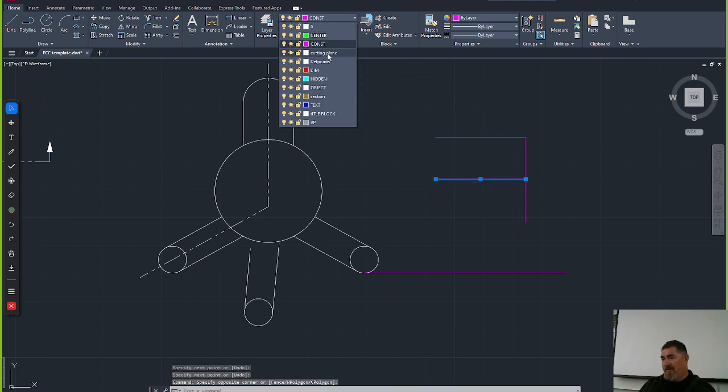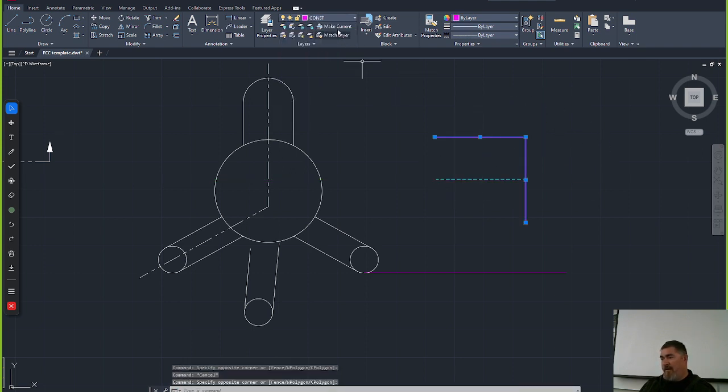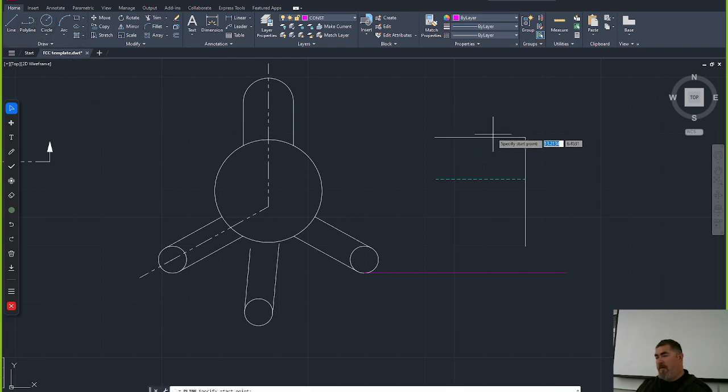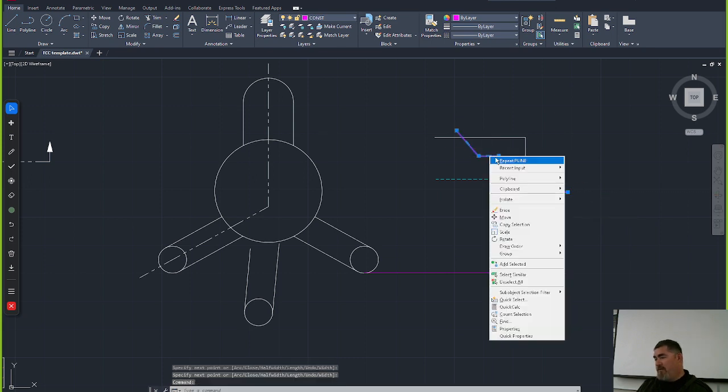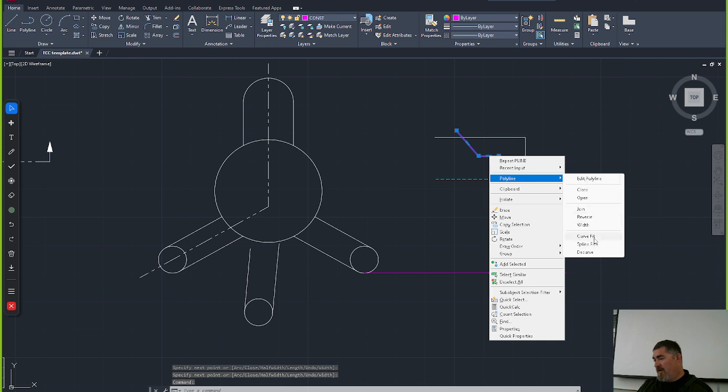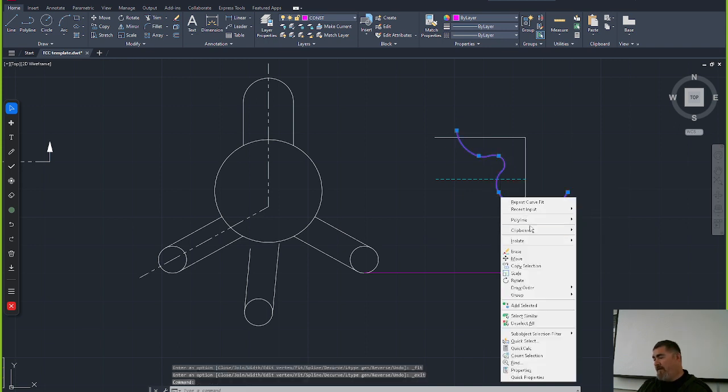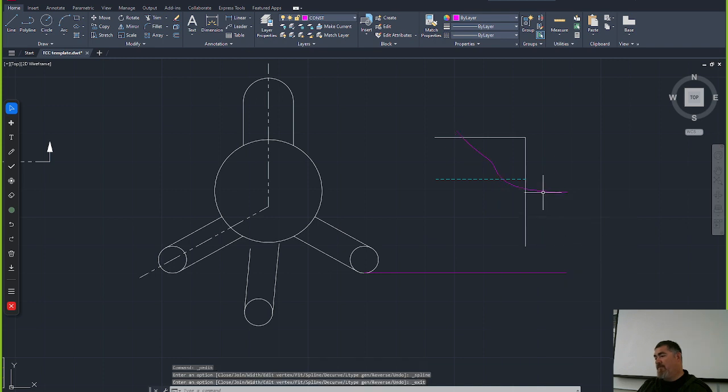this here and this, that's a hidden line. That's my object line. And I want to break this out and make it into a section, what would I do? How could I do that? Yeah, so I could draw a polyline. Okay. And so I could draw a polyline here, and then I could go into it and set it to a curve, either the curve fit or the spline fit, and do that. You can also just do the spline command,